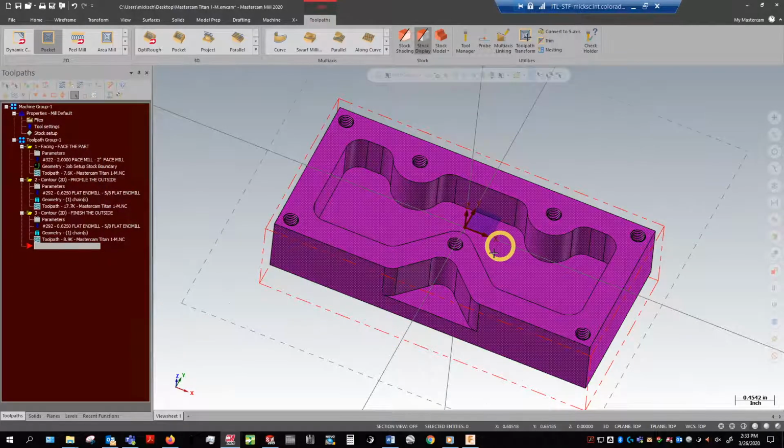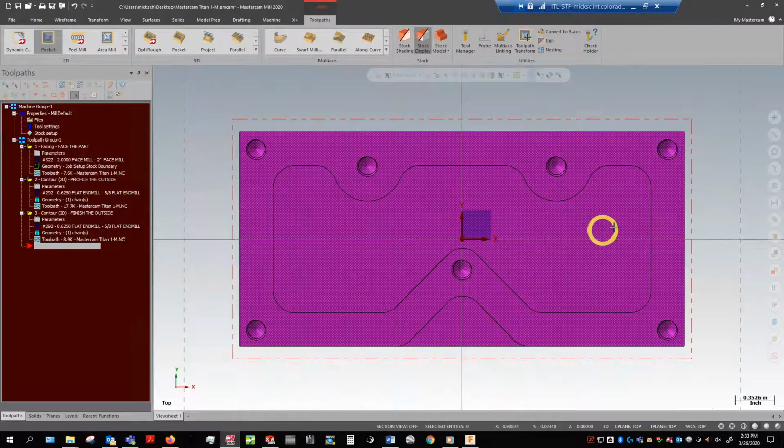I'm going to use a newer style toolpath called Dynamic Milling. What Dynamic Milling does is it looks at this contour, this feature, and it's going to make sure that when a tool is coming in here, and let's say it hits this corner right here, when it hits a corner, it's engaging the tool a lot. So when it just comes in and cuts like this, each time it hits a corner, you're going to overload that tool. What a dynamic toolpath does is it comes in and peels away, and it comes and peels away, so it's peeling away material versus plowing through it.